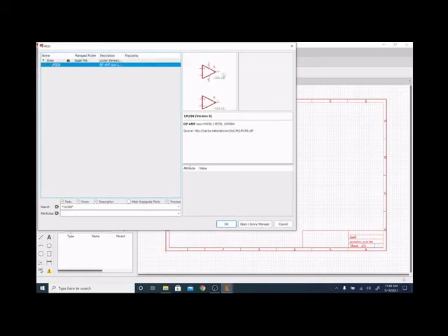So if we click that, we're like, oh great, that's what we want, but we can't add that, right? If we try and hit OK, it says we need to select a specific footprint. And what they mean is, in Eagle, you always have footprints and schematics. So what we have on the left here is a schematic. Again, that's the human visual side. This isn't actually what it's putting on the circuit board.